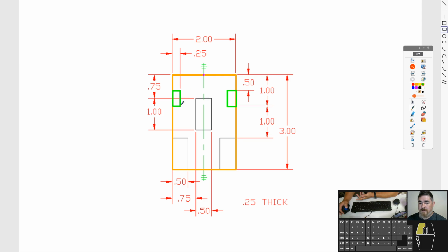these are going to be exactly the same, because I can make this line up with that line, and I can make those 2 lines be equal length. I can make those 2 lines be equal length. So then I can really just concern myself with dimensioning one side of it. The other one's just going to do what it does. Later on, if we're going to do something like a mirror, I could just do this one and then mirror it over there. But here we're just doing a sketch.